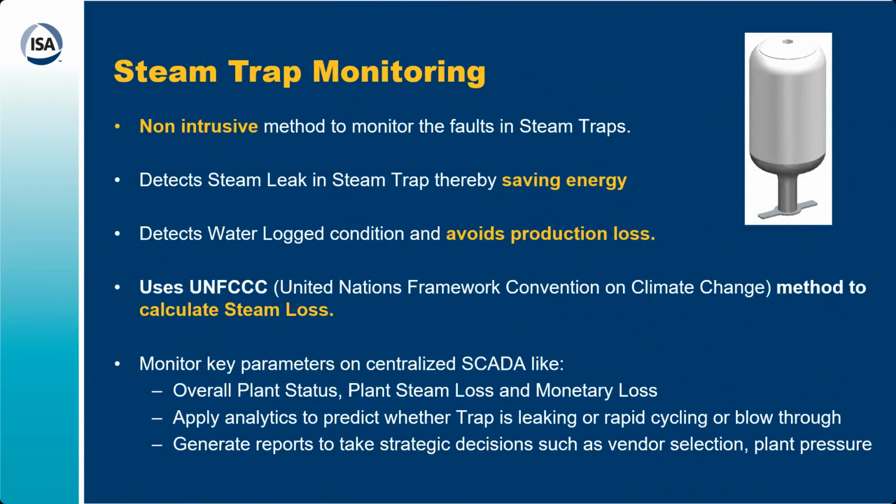Suppose on that basis you can see how many traps are failing; that will be a third party application, so it will not be the HART application. But you are getting the data on the HART network, and on that basis you are building the analytics. It's up to you what level of analytics you can do.